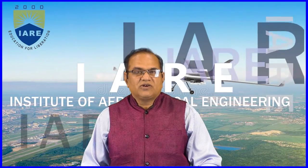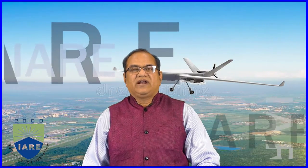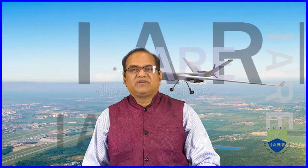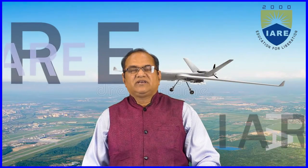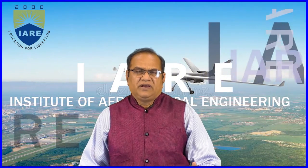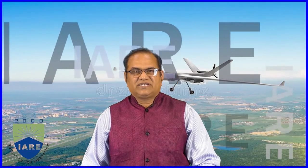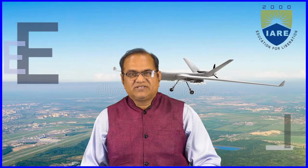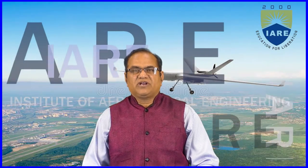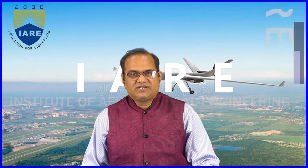In this module, we also have seen the deflection of elevator and how a trim condition of elevator can be achieved with different neutral point, static margin, and so on. In the next module, we have seen the lateral and directional static stability. In that, the vertical fin or vertical stabilizer is the major component used for directional stability.